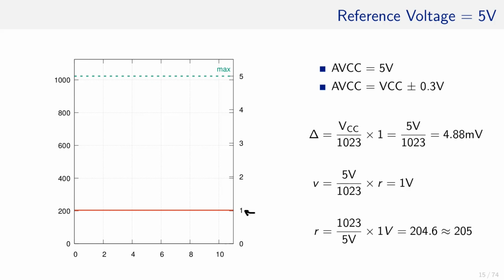Back to the example. Many times, the maximum voltage is a lot lower. Imagine a 3.3 volt sensor. Its range is between 0 and 3.3 volt, or even a sensor that returns a value between 0 and 1 volt only. Since in that case 1 volt is the maximum, it would be nice to reduce the reference voltage and hence increase the accuracy.